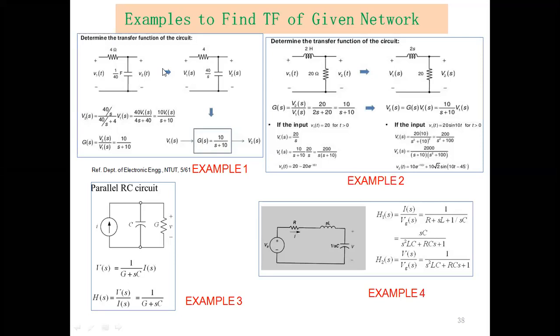You can see here, what are we doing? We are supposed to calculate the transfer function. For this, look at the first block. The question is to find the transfer function, and we have an RC circuit. Now this is the function in the time domain. But when we use the transfer function, we are supposed to use the frequency domain. So firstly, we convert this circuit into the frequency domain.